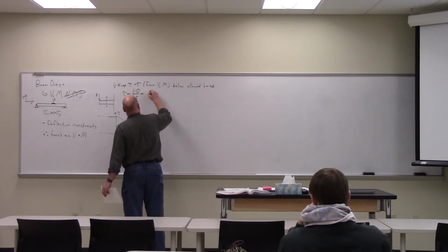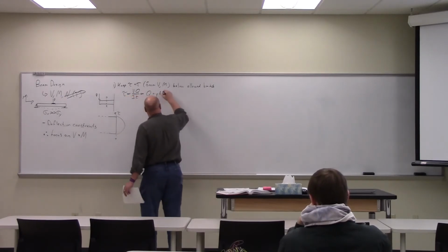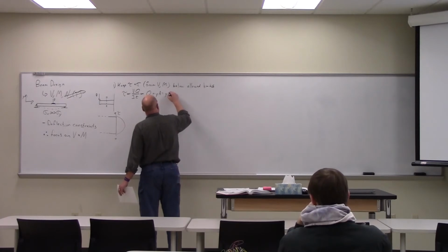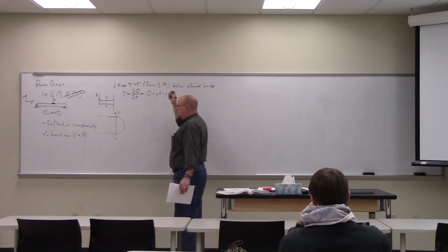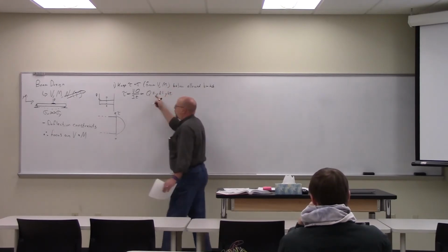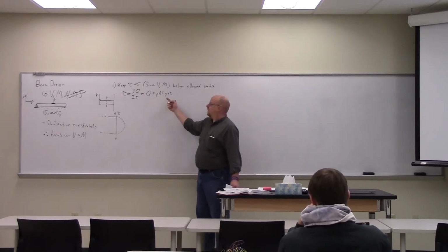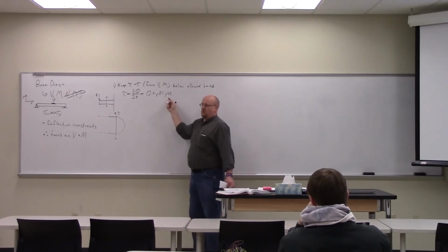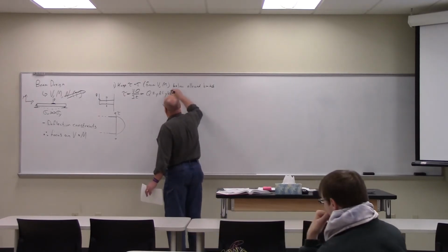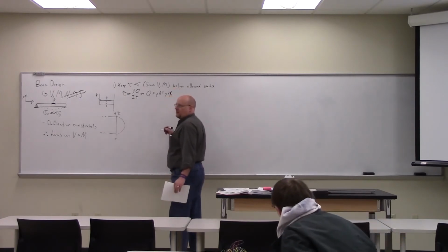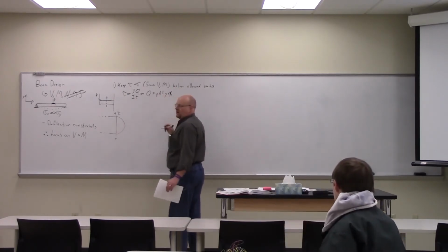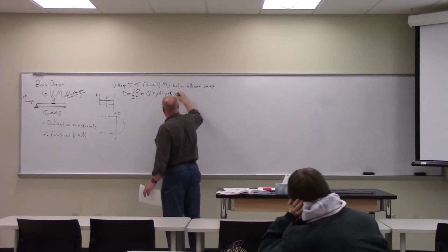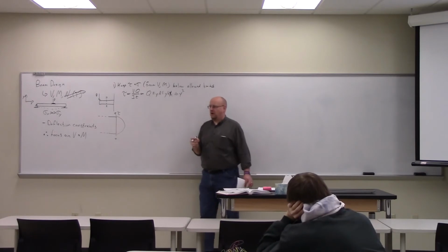Assuming it's a uniform beam, tau is proportional to Q, which is equal to Y times the area, which is equal to Y times H times T, approximately. If it were a rectangular cross sectional beam, then these would be exactly equal. Well, T is uniform across the whole thing, so it goes away. So effectively, tau is correlated to Y times H, which is essentially like Y squared. That's where we get the parabolic behavior.